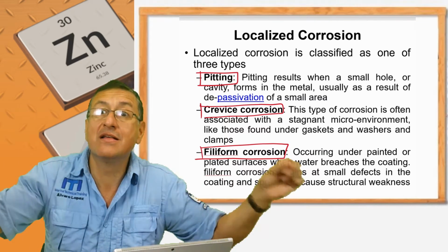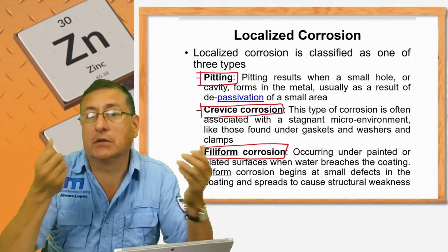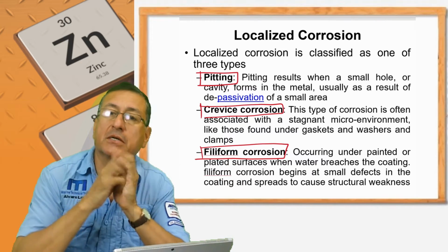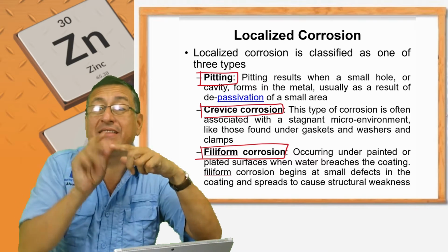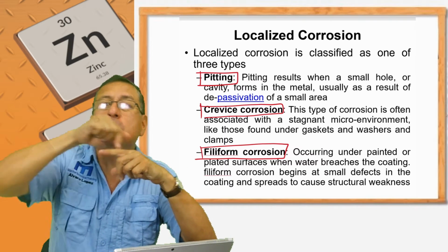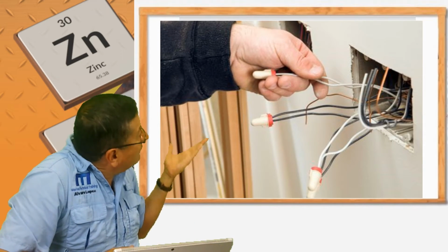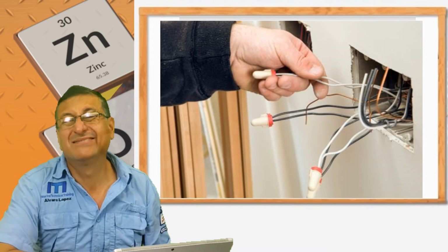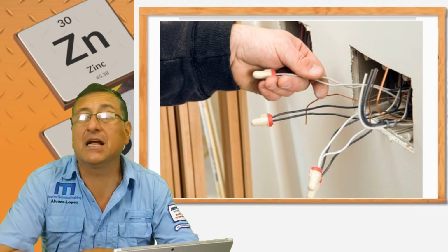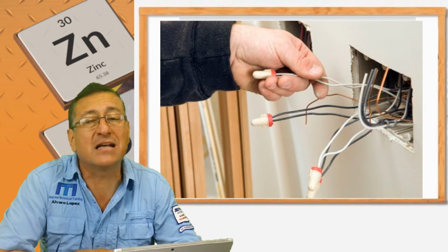The wire is marine wire, marine approved wire. The terminals all have heat shrink and no humidity penetrates. In residential applications you have that situation with the wires. Those Mickey Mouse terminals are not accepted in marine applications.